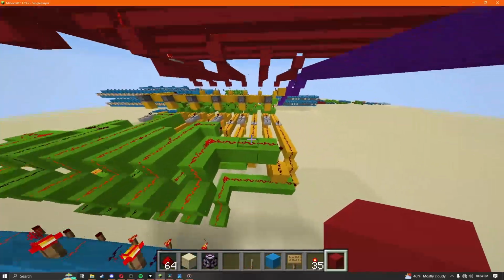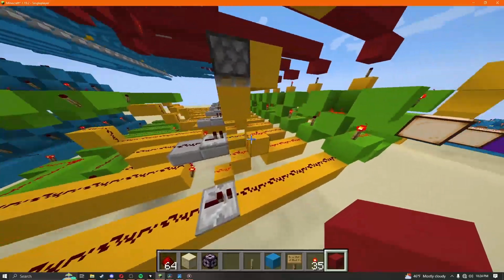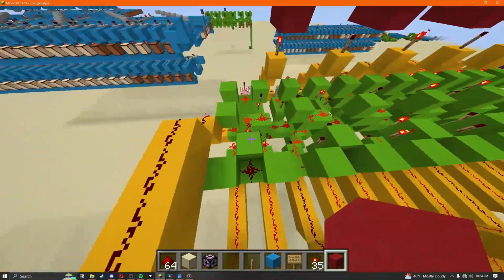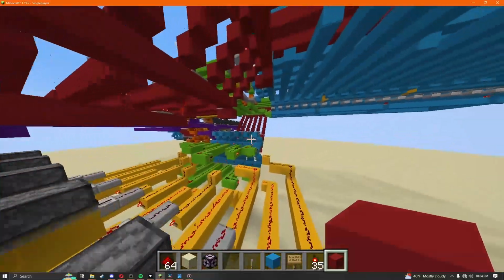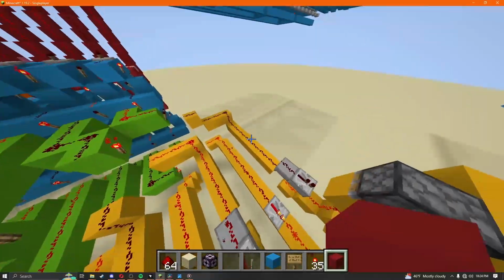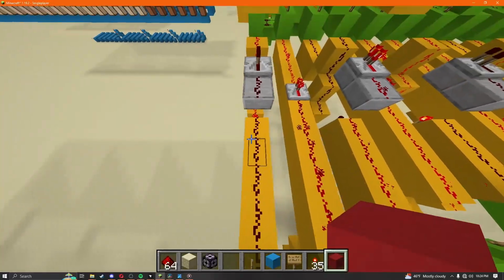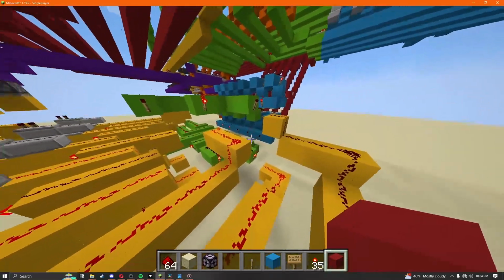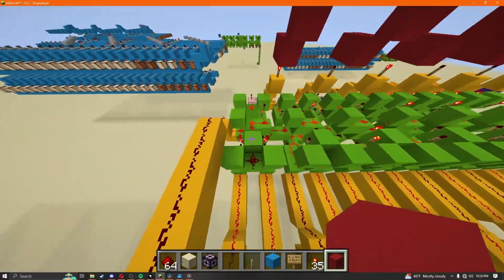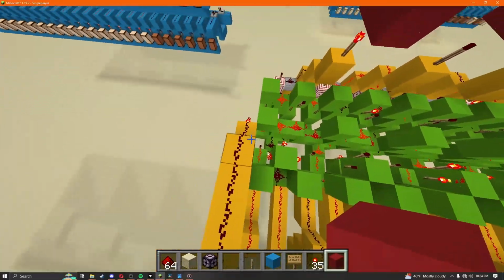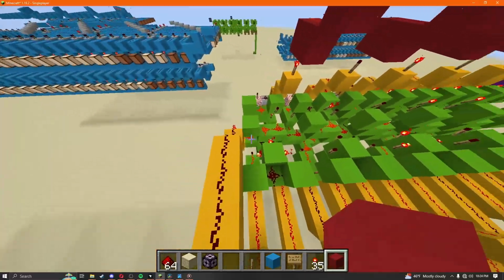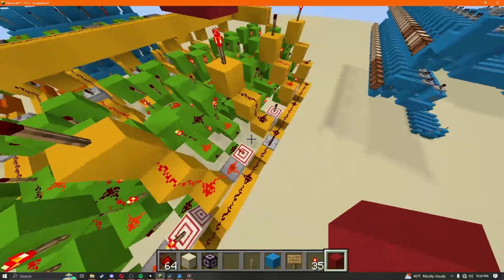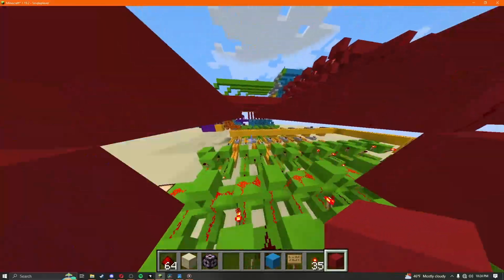Next, these get put over to here and get sent into our adders. The way these work is every value goes to every other one, so this is the least significant bit of the top register, and this is the least significant bit of the bottom register down here. They get sent through and added. So we have our 2 inputs and a carry in, and we get our output on the bus right here, which gets sent back up to there.